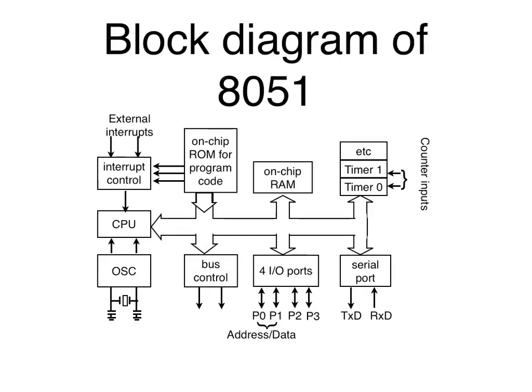And so this is the block diagram of 8051, or at least the classic 8051. New ones are called 8051 compatible, and their architecture is going to look slightly different, but overall it's the same theme. Okay, so what do you have? Well, you have the CPU or CPU core, which is in the middle left part. That's just a small little component of it.